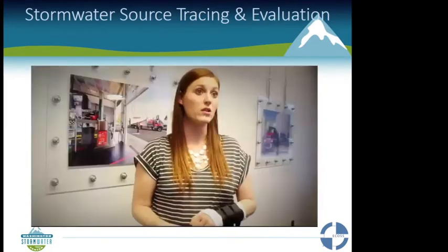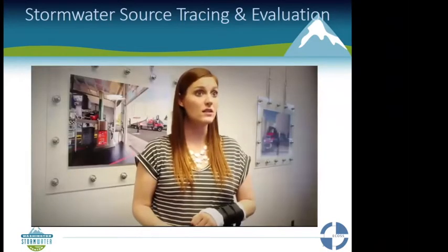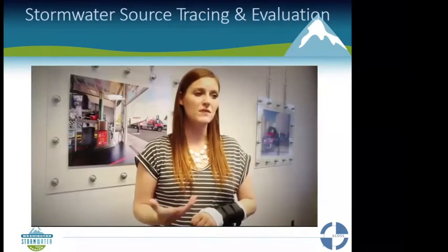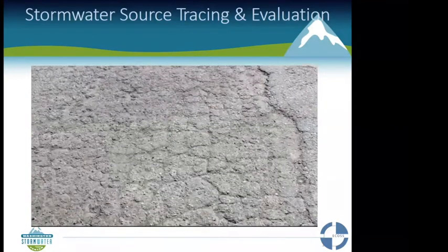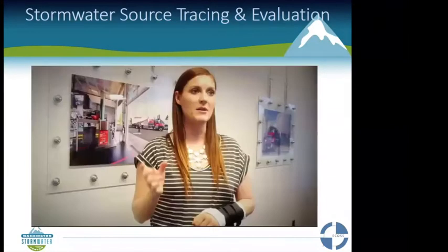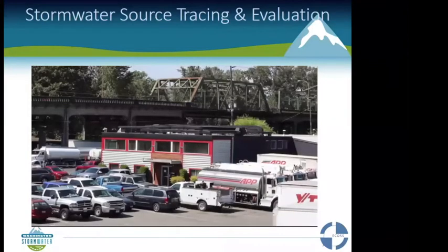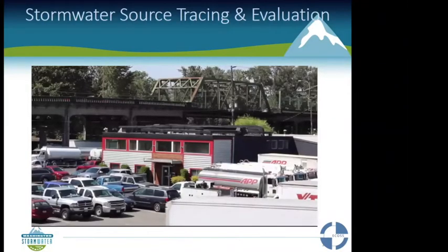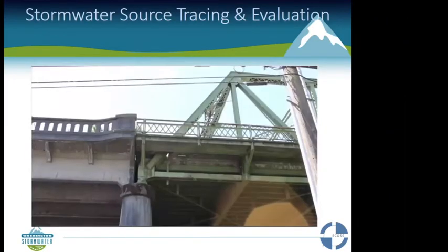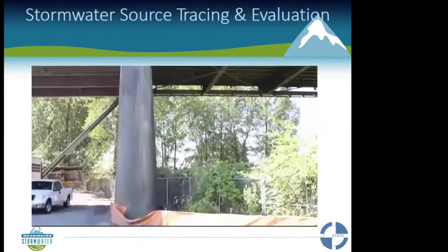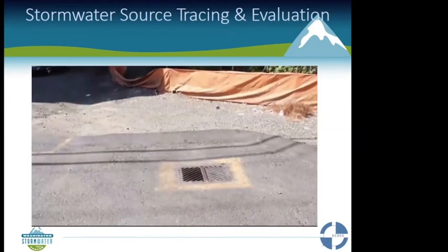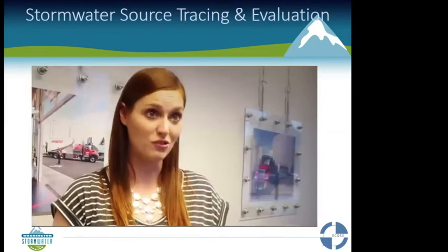And even though we are doing sweeping every 2 weeks, I was still seeing that there probably was an accumulation of zinc in the cracks in this asphalt. I took a look at a particular catch basin in the back corner of the property, which happens to sit directly underneath the Puyallup River Bridge, and thought that that could be a culprit for some of the zinc issues that we see here too. So I sampled that catch basin, and sure enough, it was extremely high.